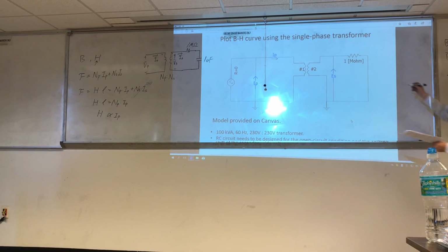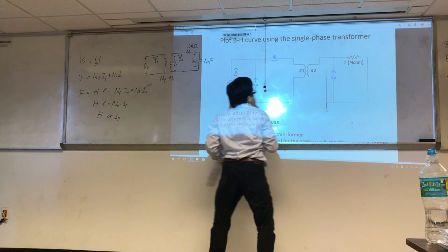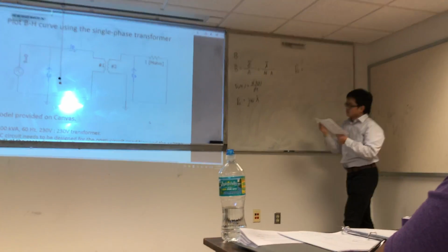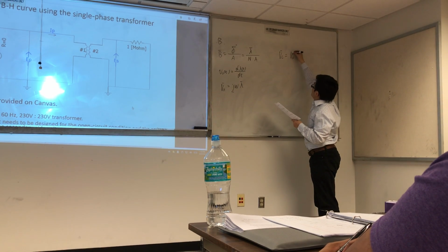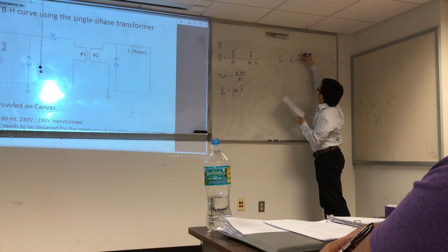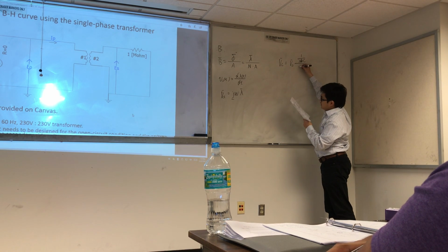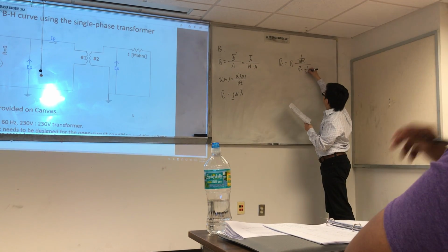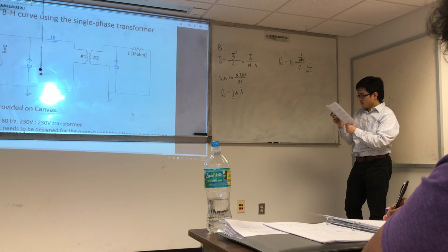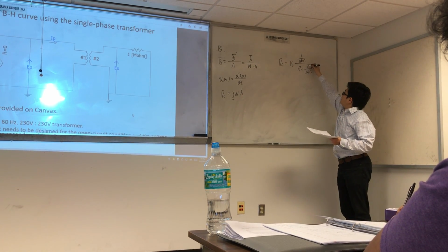Okay, so the voltage on the capacitor is Vc. What's your Vc? Vc is Vs times the capacitor impedance over R plus 1/(jωC), so we can use voltage division. We know R is much larger than this part.